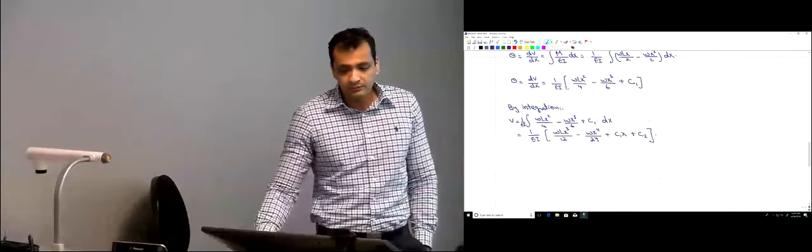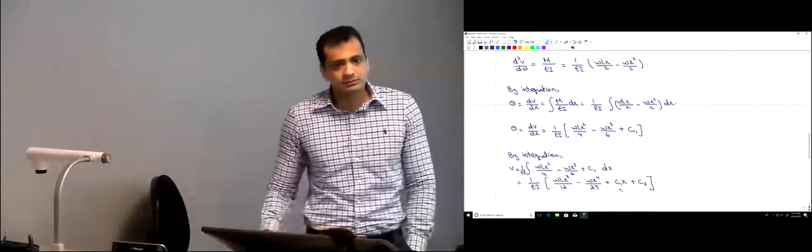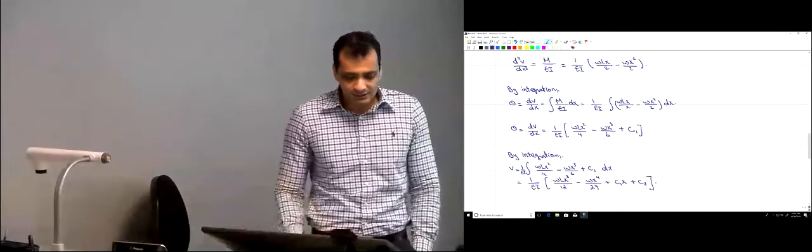I asked you this and you answered it correctly before, but you just forgot that you know this now. No, W. You know W, okay, but this is not gonna give you C1 and C2. L. You know L, but again, it's not gonna help you, okay? And instead of just having W here, you're just gonna put 4. Instead of having L, you're just gonna put 10. Reactions. The equation for the deflection has nothing to do with the reactions. Right?